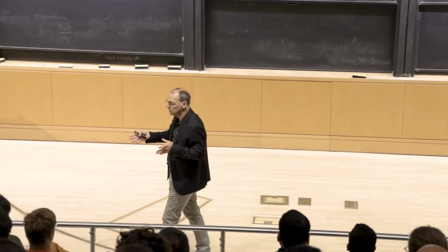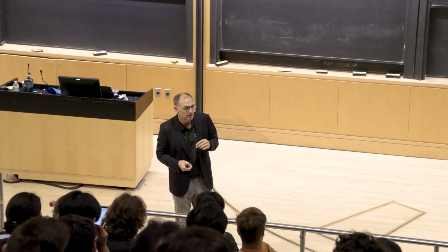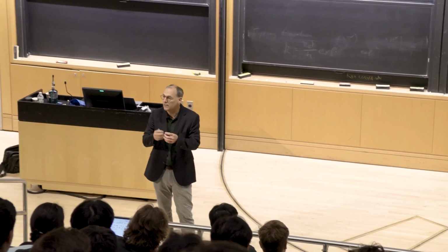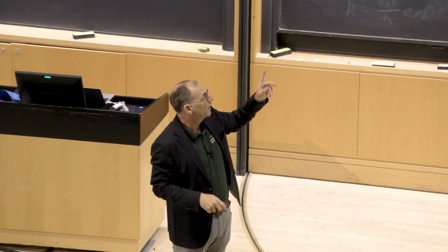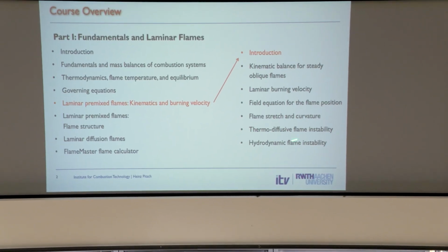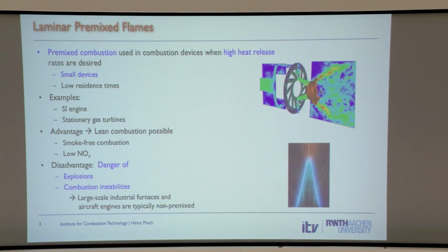And then there are so-called intrinsic flame instabilities, which come only from the flame itself, nothing to do with the surroundings. This is what we're going to talk about here: thermodiffusive and hydrodynamic instability. These are intrinsic instabilities. It just comes from the flame.